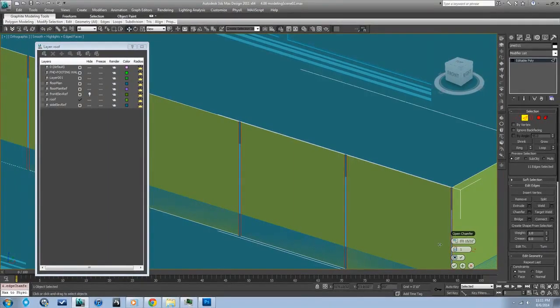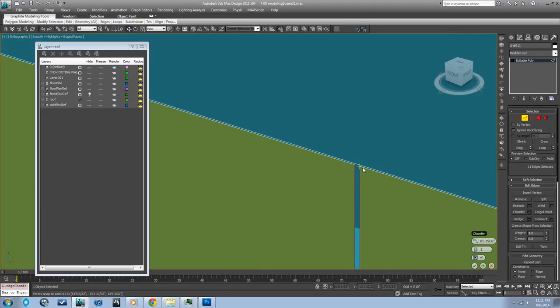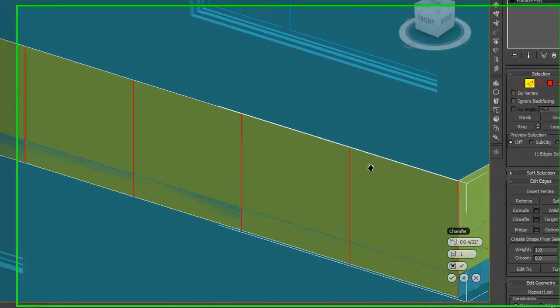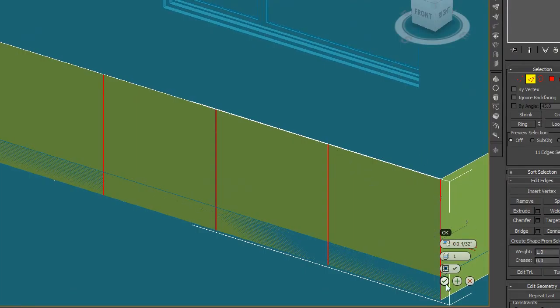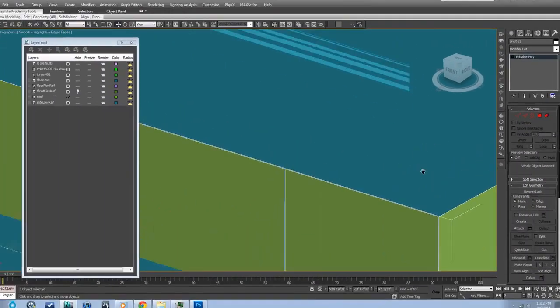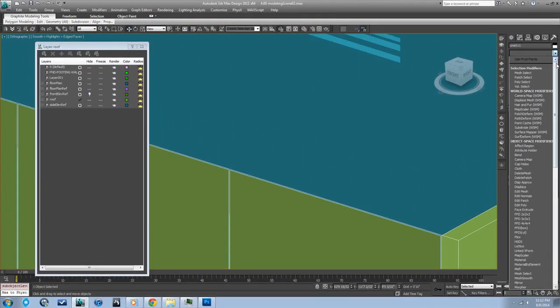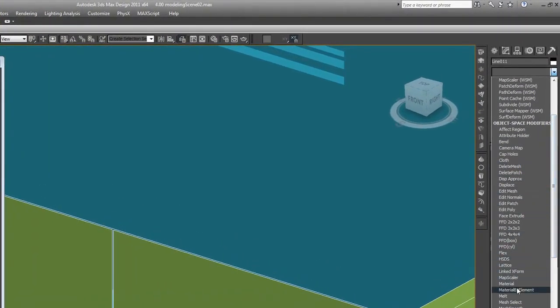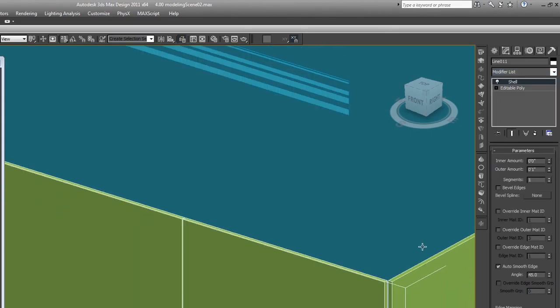If you check this here, that means it's going to open the chamfer, which means that it actually deletes the face that's created in between here. And that's how these glass face mounted railings would be. They would just be pieces of glass that butt right up to each other like that. And then to give this thickness, you could just do a shell modifier. Like that.